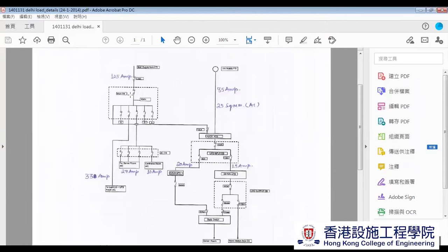So you can see the main supply coming from here and the kilowatt hour meter there, as I mentioned. There are 1, 2, 3, 4, 5 circuits there, or actually 6, right? There's another one going out from here to there. But of these 5, one goes for the UPS, which is 33 amp. There's another one here that goes through this small air conditioning distribution board.